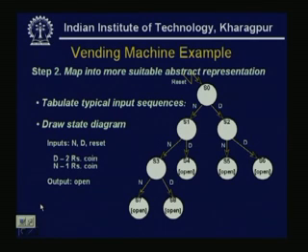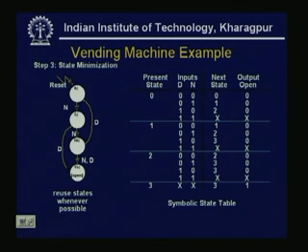See, S0, S1, S2 and S3. Only these are the intermediate states from where, with one input, one ticket can be delivered, and all are output states. So, if it is the S0 state, we have already seen, I can give 0 0, meaning nothing has been deposited, obviously the next state is 0, and the output is no output, 0.